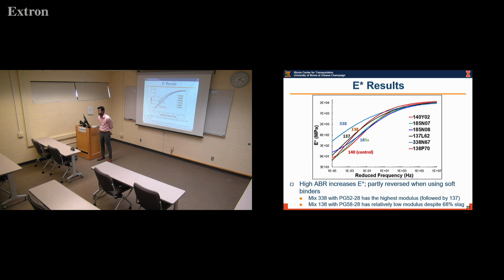But if you go to this, cores are sometimes also used for quality control or forensic investigation. You should not really target just one area, because you are basically representing the entire construction, right? If you just get your cores from a very limited area, that may not represent the entire section, if your objective is to characterize the performance of that mix. You may not just focus on one small batch. Maybe that batch is one replicate, but you move to another batch, maybe 100 feet from that location, and get another sample. That can represent the overall use and production of that mix.